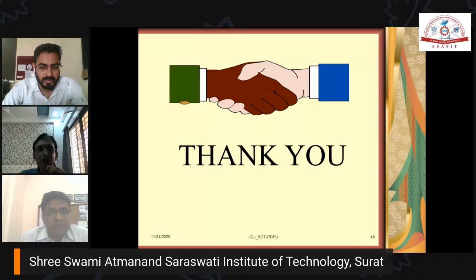So what are the main requirements of the smart grid? The smart grid should be able to integrate the low carbon energy sources or the renewable energy sources. So we are talking about solar, wind. These are nothing but low carbon energy sources. Now, on the smart grid, you know that there would be harmonic problems because we are using power converters. So harmonic control, voltage fluctuations, variations in the voltages, variation in the power, and also protection issues may arise on the smart grid. And smart grid is designed to achieve sustainability, reliability, and increased efficiency of the production and the distribution of electricity.